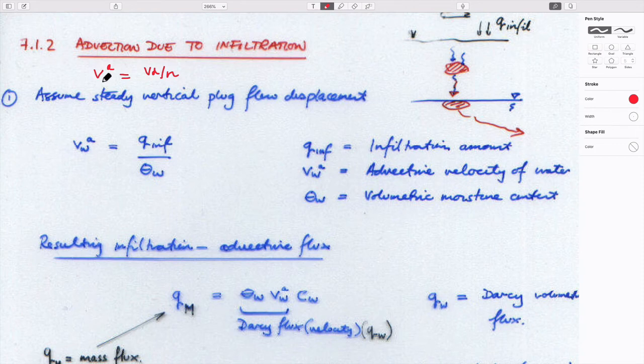So this is, we've called it aqueous, I guess, right? It's confusing. So this is aqueous. And the idea is that the Darcy velocity gives you the bulk flow. It's only flowing through the cross section, which is the porosity. And so porosity is always less than 1, so it speeds up the actual flow relative to the Darcy velocity.